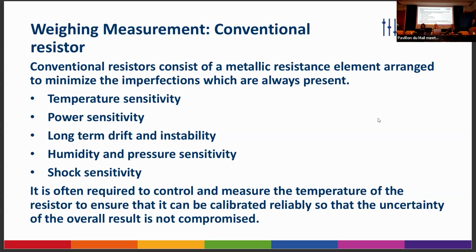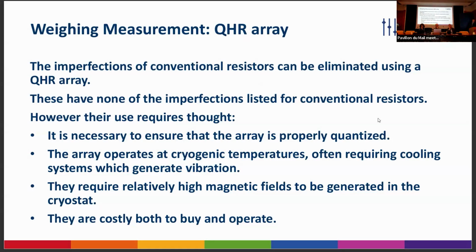But one of the important things, though, is if you are controlling the thing's temperature and you have to carry it from where you use it to where you're going to measure it, you need to ensure that the temperature control system and everything else does not change as you move it, because effectively, if that happens, you get a value at the calibration end, which is not the value used while you're measuring. And that is very difficult to find. So you need to think very carefully about how you're calibrating these devices.